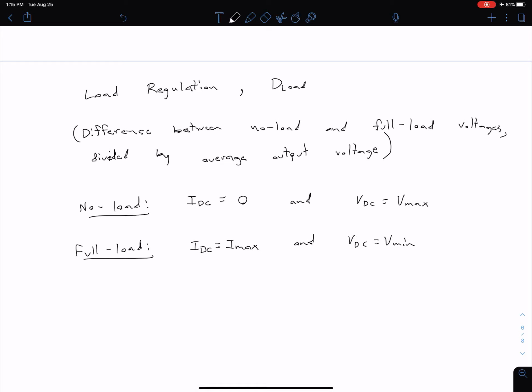And so this might be a confusing concept of changing the load and getting different voltages from the output, because oftentimes we're just talking about ideal sources or ideal voltages, ideal components. But in practice, of course, we have a finite amount of power that can be supplied by these devices or these sources or batteries. So what that means is, as we connect more stuff or larger loads, we're actually going to see a decrease in voltage.